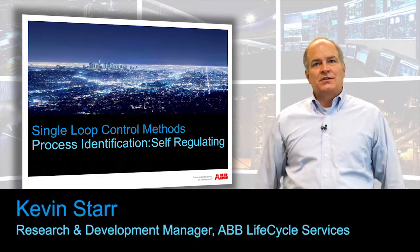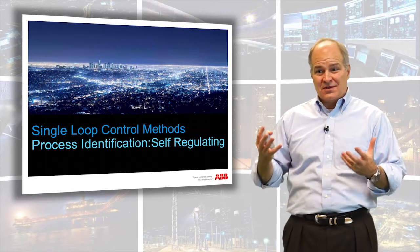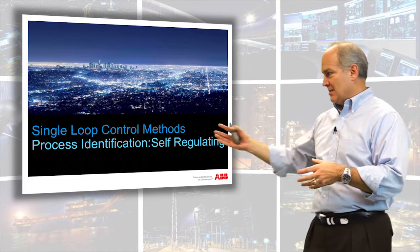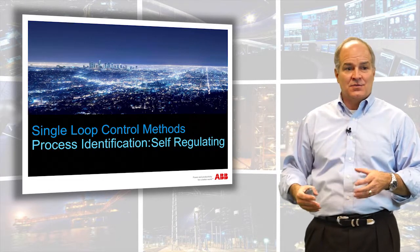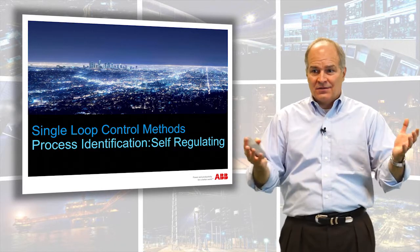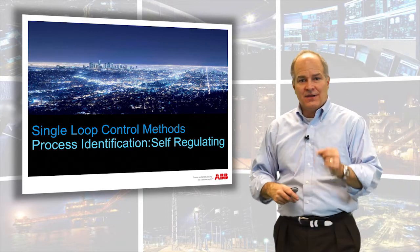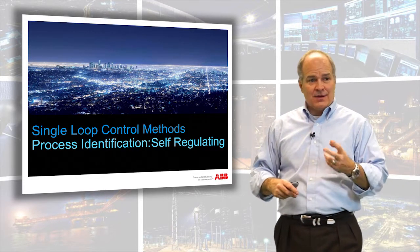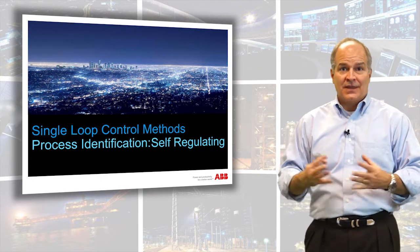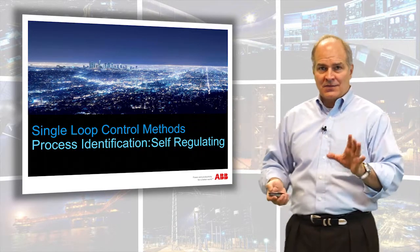Hi, in this session we're going to talk about how to take a bump test and convert it into numbers. Those numbers are what you use to come up with tuning parameters. So hopefully you're coming into this session on self-regulating process identification with an actual bump test, where you have a printout, which would be ideal, or something in Excel or some numbers, and if not, after this you'll be able to go and do that. But we're trying to identify two numbers that represent how the process will respond if I inject energy into it. That's the trick. Once you identify that and it's repeatable, you can tune anything, and that's the first step.